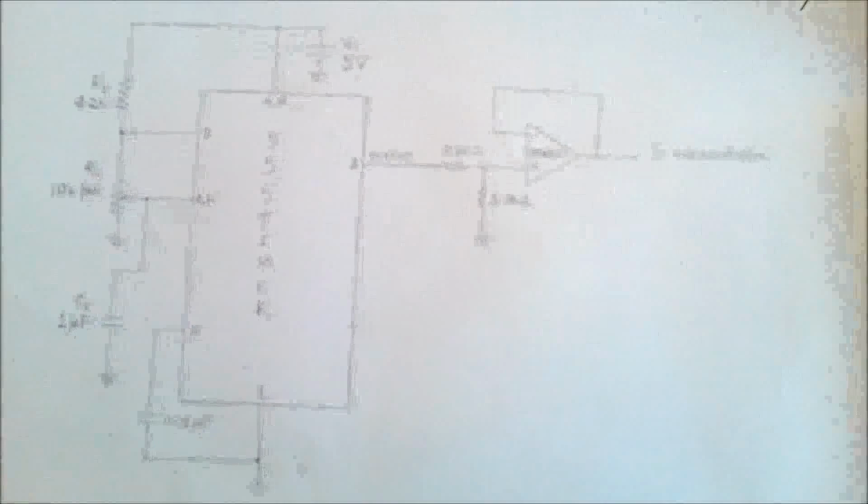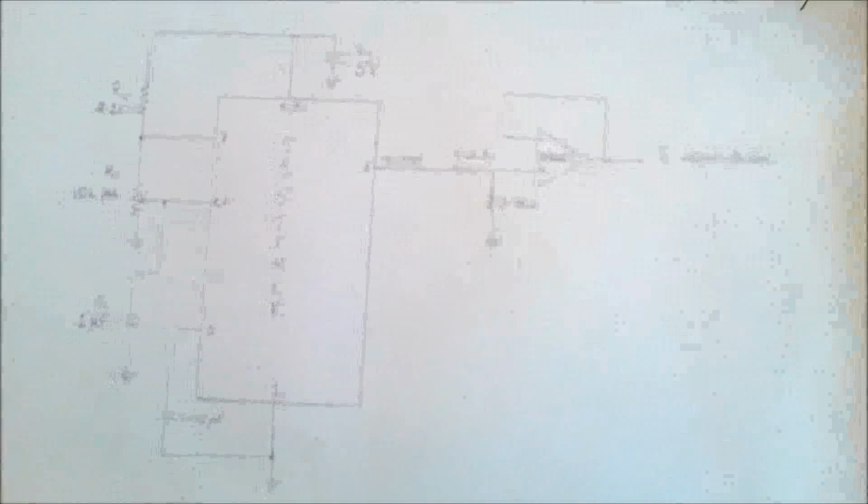To achieve this variable frequency, we are using a 10 kilo ohm potentiometer. The varying frequency represents the varying speed. The output of the velocity sensor is fed to the microcontroller, which counts the number of pulses. When the frequency is high, it means the number of pulses is more and hence the vehicle is moving at a higher speed. The reverse is also true.